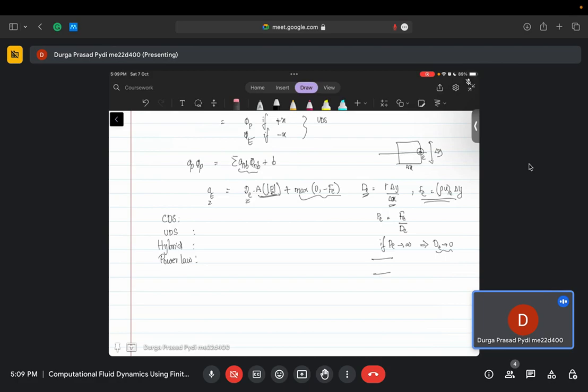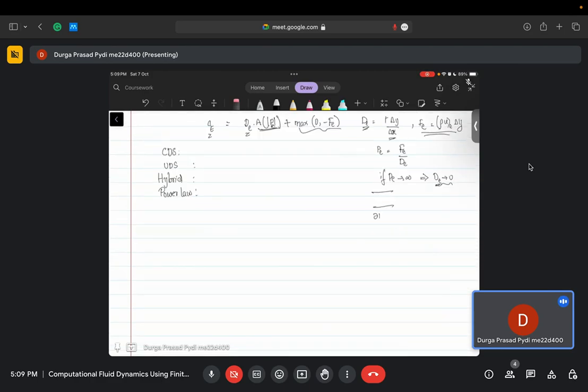Even in a parallel flow heat exchanger, though the equations have a diffusion term in them, when it is dominated by convection, you can assume it to be purely convective and ignore the diffusion terms, and then the problem becomes very similar to time. So even though you have space derivatives, dou T dou x, you can assume x to be a time variable, and then you can use any of our methods like Euler implicit or explicit form, or the Crank-Nicolson scheme to solve the problem. Very similar idea is being used here.